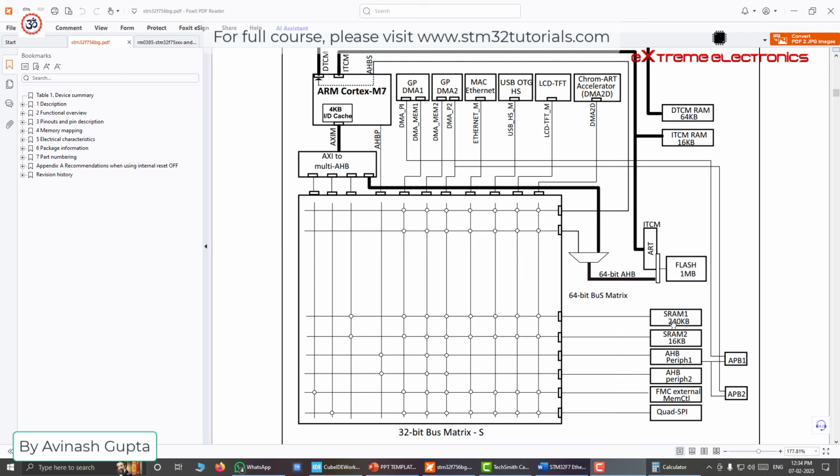But sadly this is not possible in this microcontroller because the SRAM2 is very limited, only 16 KB. And the 16 KB will be used up only by the heap memory, and we are left with no more space for the pool memory. So in this microcontroller we can only put either the heap or the pool inside SRAM2. We cannot fit both of them inside SRAM2.